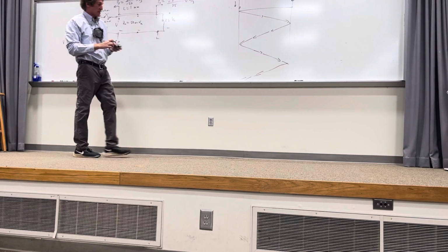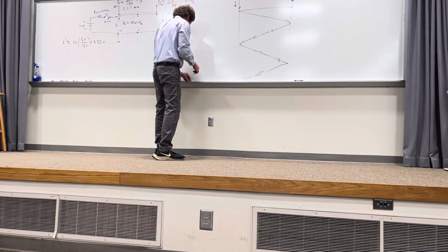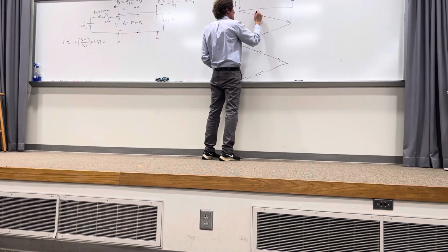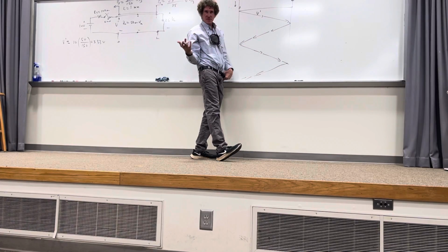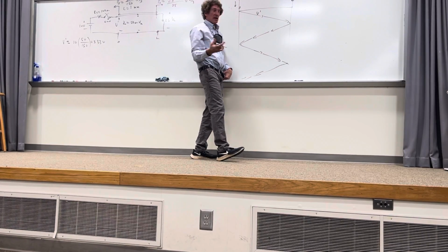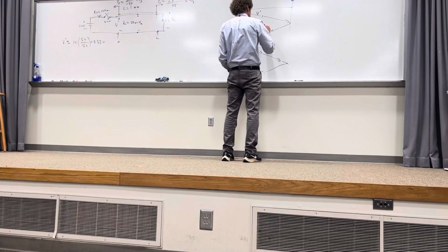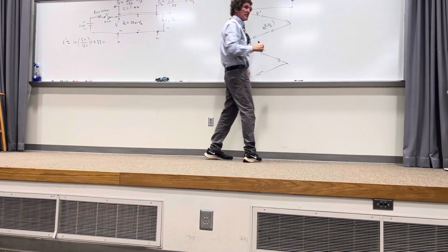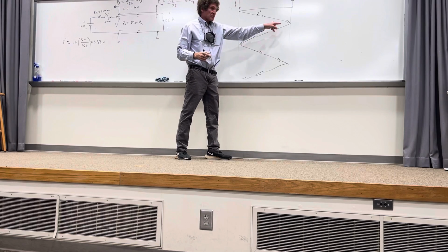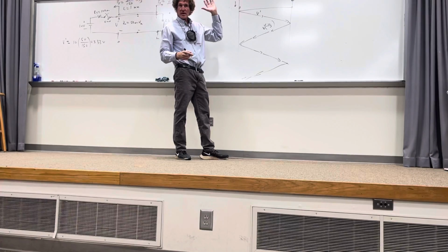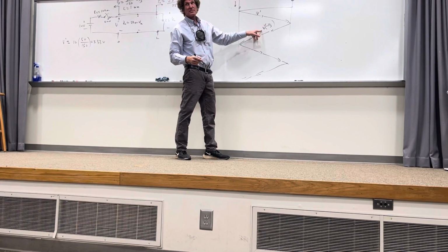Now we just go down here for this timing diagram, and when I look here, this is my V prime, which is 3.33 volts. I'm going to leave it as just V prime for now. Coming back this way is going to be V prime times minus 1/3. Y'all agree with that? Everybody? And that's the thing reflecting this way, correct? Y'all with me on this, class? How many see this? I'm sure you do. Now I could put minus 1/3 times 3.333, which should be minus 1.111, but I'm not going to.